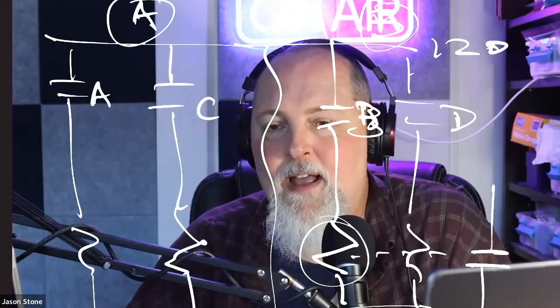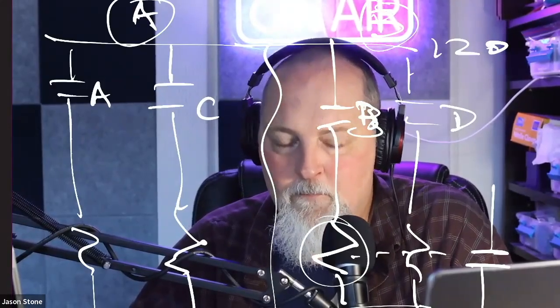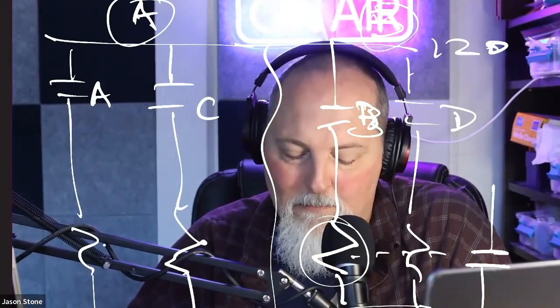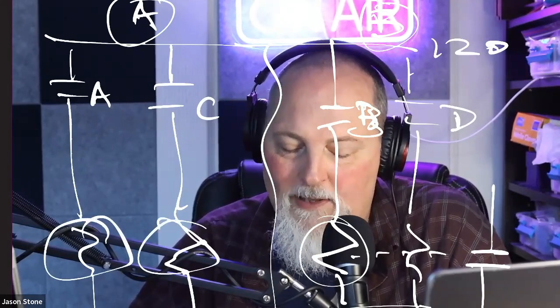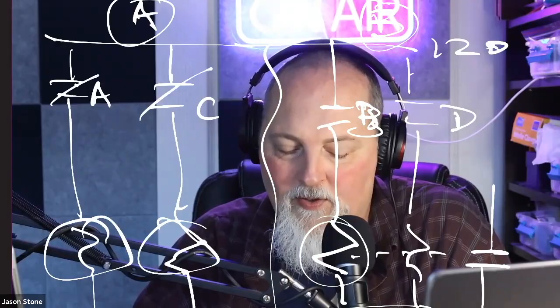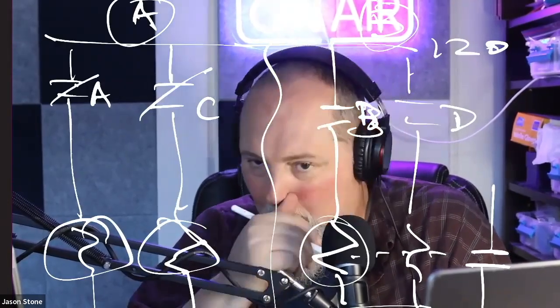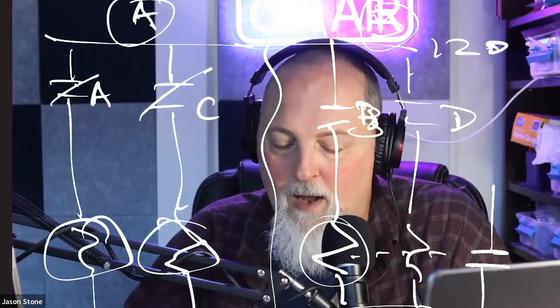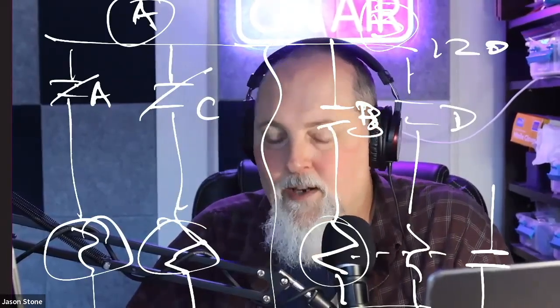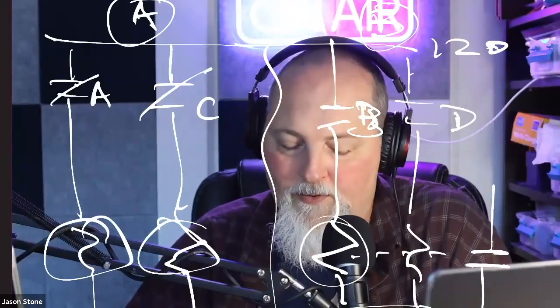And so if I have a 2 of 2 taken once, then that would mean I need both this relay and this relay to actuate. I would need this contact to open or close and this contact to open or close to say, yeah, hey, we really got a signal. And if Bravo and Delta don't do anything, then it doesn't matter. I've at least got 2 of 2 taken once.